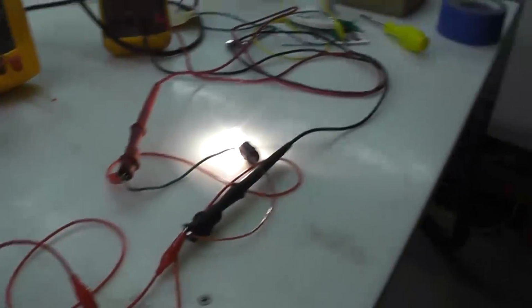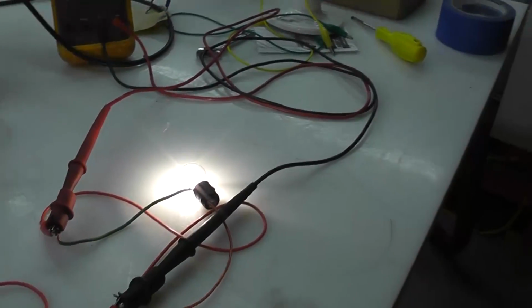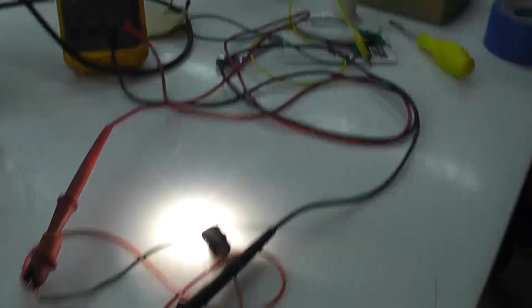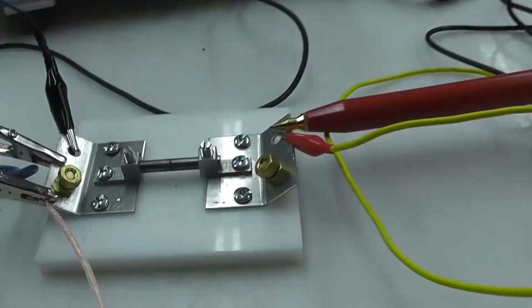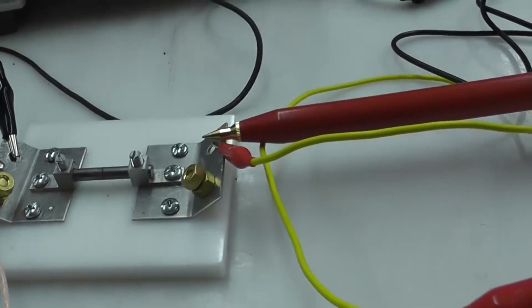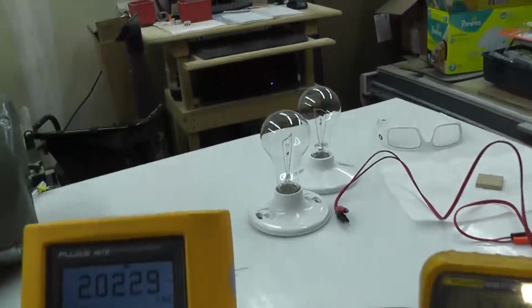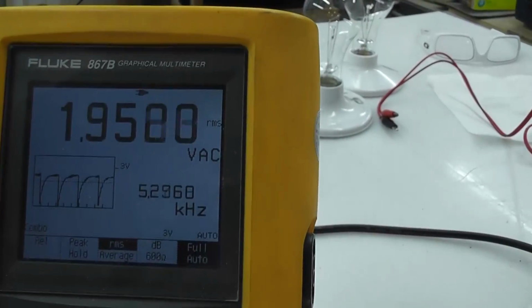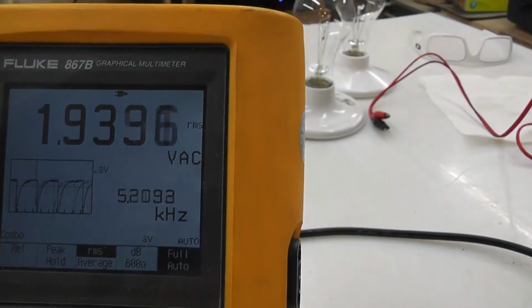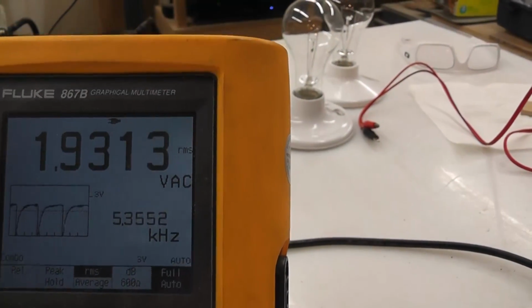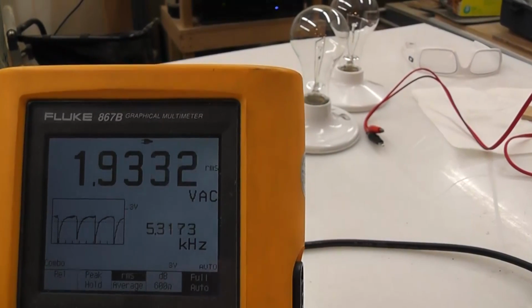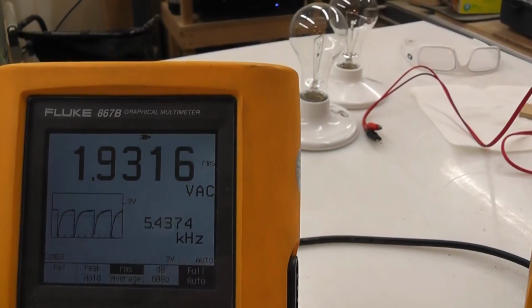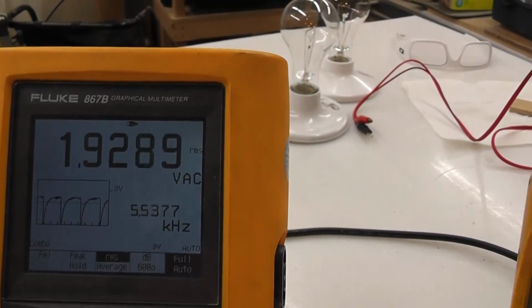Okay, so light bulb on, burning really bright. Now I changed this capacitor like I said I was going to do, and this has got a higher pitch squeal now, and here's our reading on the meter. You can see now it's at 5.2 kilohertz ish, and almost 2,000 volts, so 1.9 times 1,000, remember, about 2,000 volts.